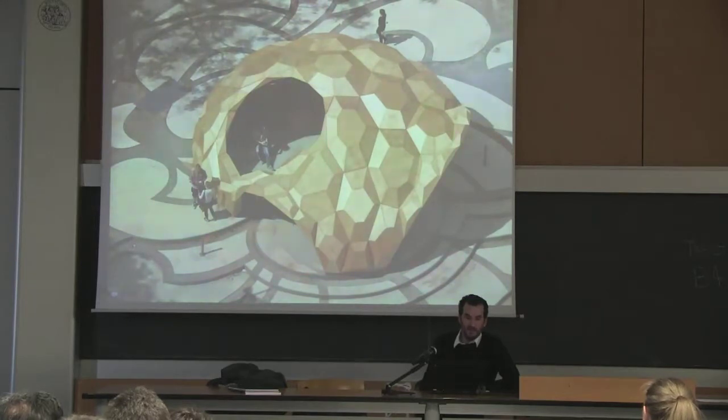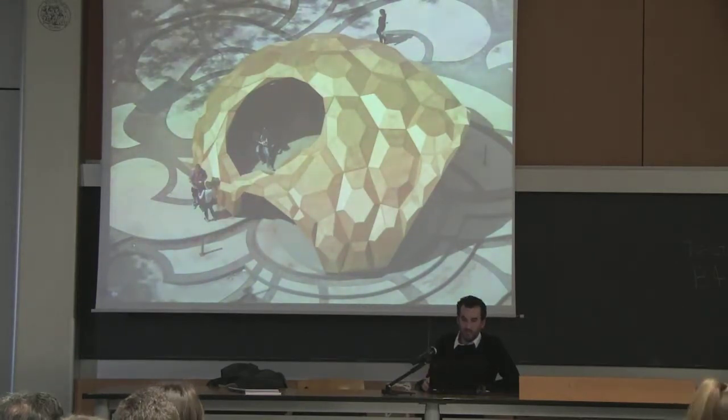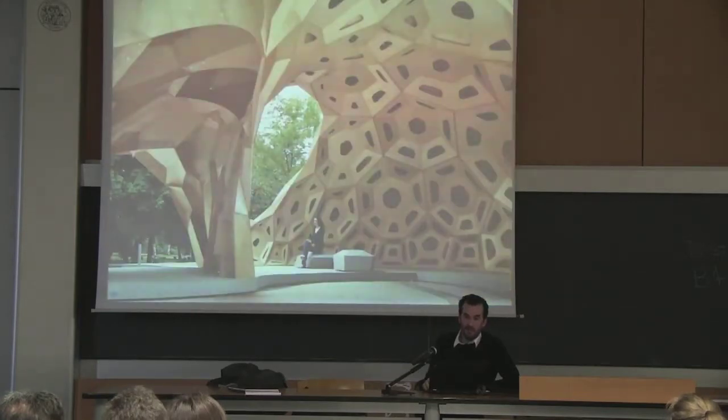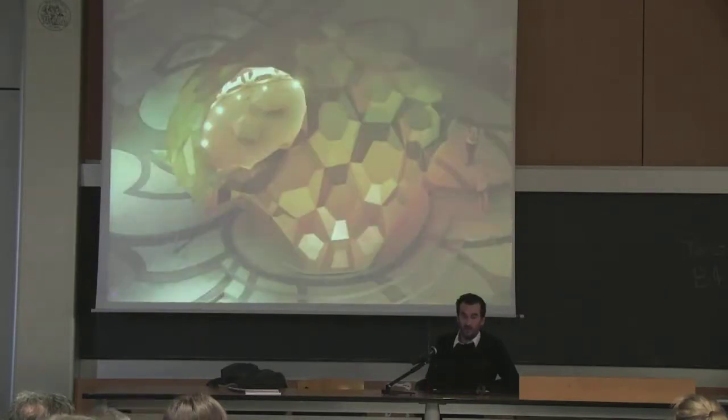Again, more importantly probably, is that this quite unique modular wood shell demonstrates a high level of structural possibility, but also quite a unique architectural potential. And all that with a system that is really only made from plates that are connected with these finger joints. So there's no other connection. So here, again, the amazing thing is that the structural capacity was demonstrated by using only 6.5 millimeter plates. So this entire system, everything you can see on that slide, was actually built by using less than 2 cubic meters of wood. So I think it's a nice example of how an expressive architecture does not necessarily mean an excessive use of material resources.